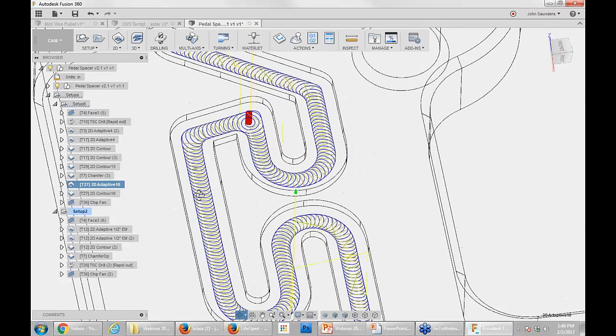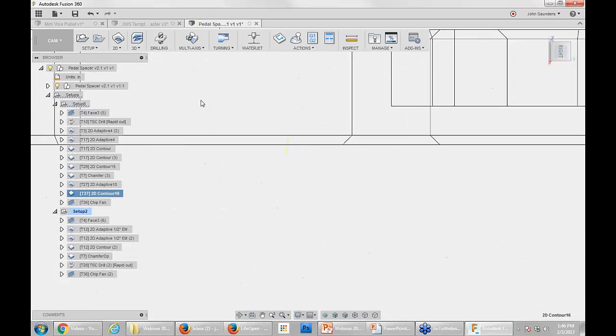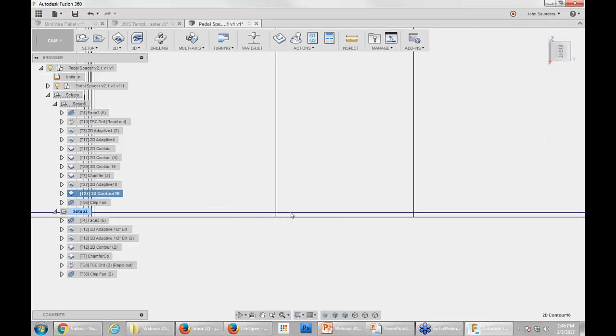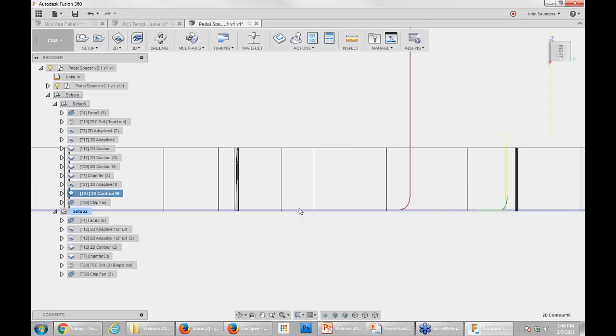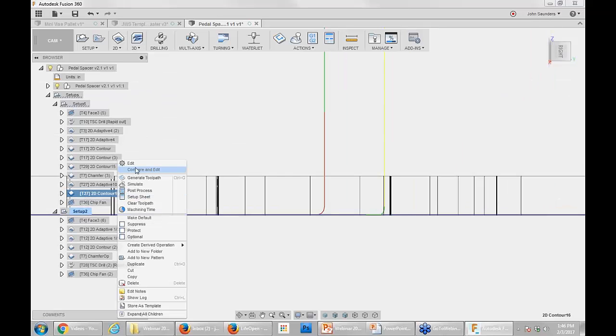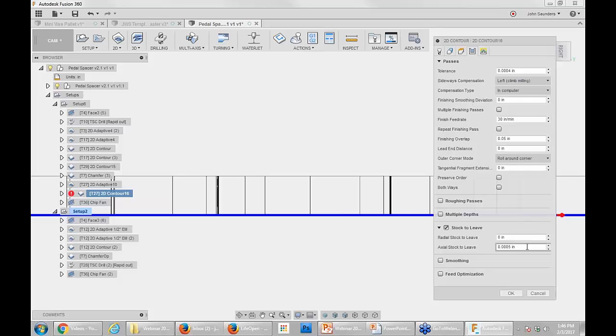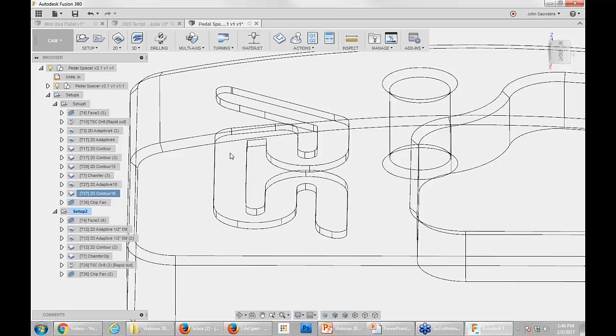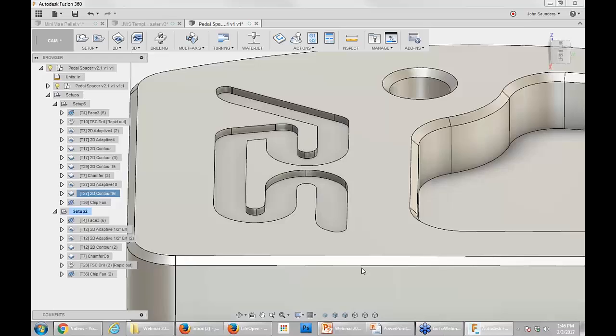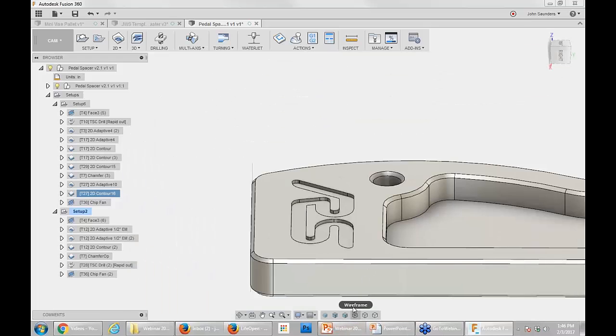So for instance here, that's showing a trick I like to do, which is I'm adapting out this logo, but when I come back in for the contour, see how in the wireframe view you can see that that blue toolpath or the control point is actually up off the bottom of the part. It's actually only 0.5 thou, so there's no practical implication to the functionality of the part. And by staying 0.5 thou above it, you avoid that little drag line that you often see where it looks like somebody traced a tool around the periphery of the thing. And then switching back into shaded mode is really easy, again, with that little toolbar pop-up.